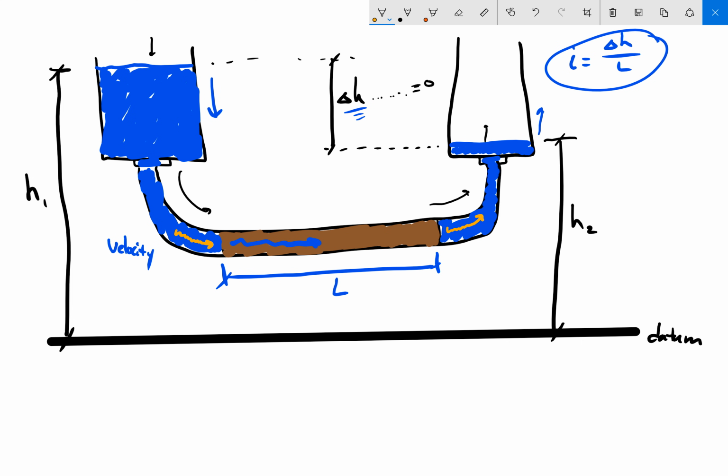Okay, well that's great. So I know then that flow is simply equal to velocity times area. All right, so flow has got to be constant in the whole system. This area, right, is the cross-sectional area where our fluid is flowing. Now, in the pipe, where I have my first orange arrow right here, the pipe is not clogged at all.